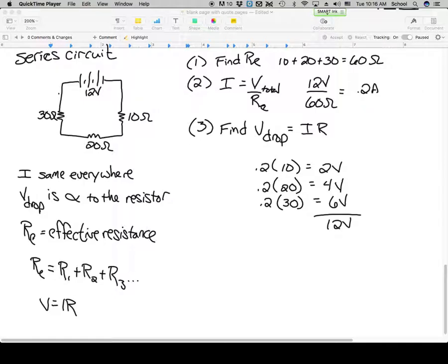So then we get to the part where, say this is wire A and wire B and wire C and wire D. Now, if we want to know what is the voltage in the wire, when we first come out of the battery, the voltage is full voltage. So if I would connect a voltmeter here and connect that to ground, this voltmeter would read 12 volts. If I would connect a voltmeter at B and connect that to ground, that would read 10.